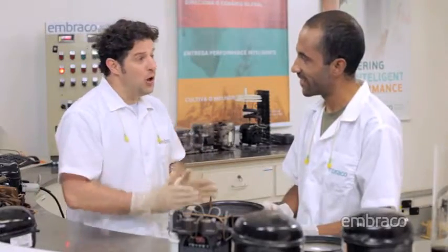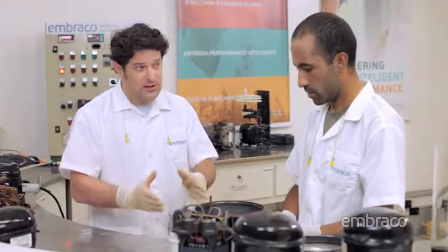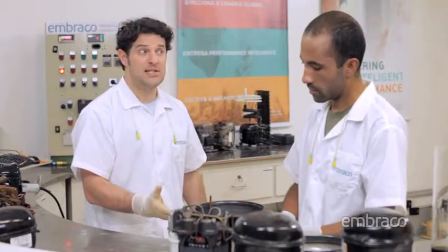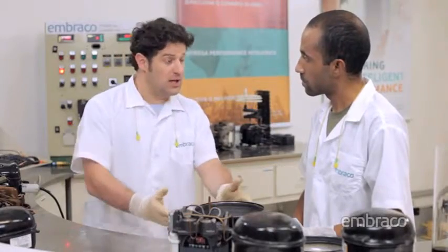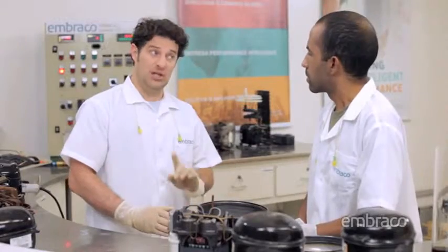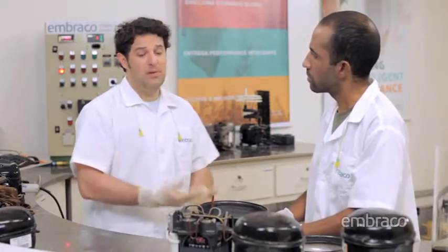It's true. Compressors leave Embraco's factory with the ideal oil charge for flawless performance. What happens is that during the cooling cycle, the oil mixes with the refrigerant fluid, causing a fraction of the oil to circulate through the cooling system and back to the compressor. But when there's an obstruction in the tubing or problems in the system's sizing, the oil can't return, causing the charge to be less than ideal for the compressor's optimal operation. What would these sizing problems be?